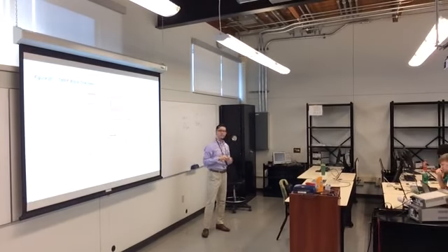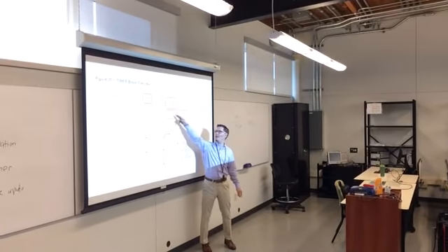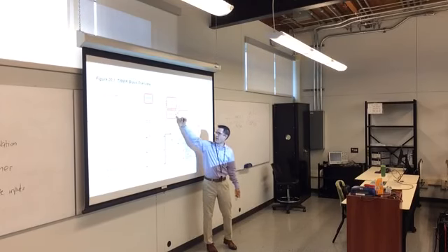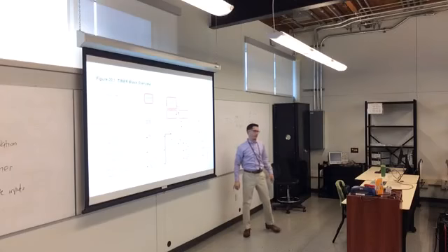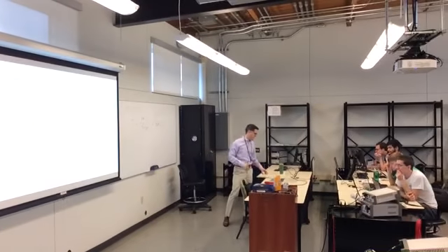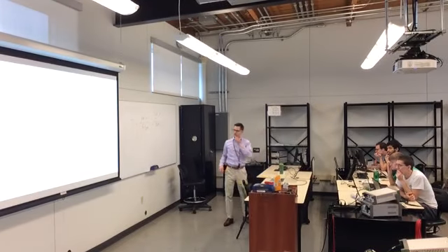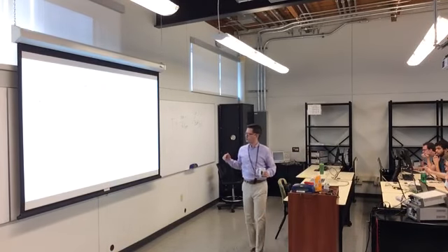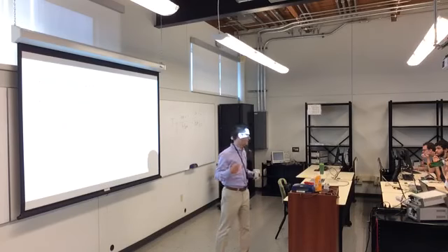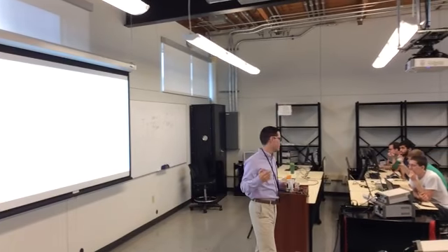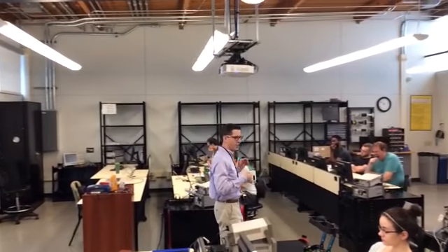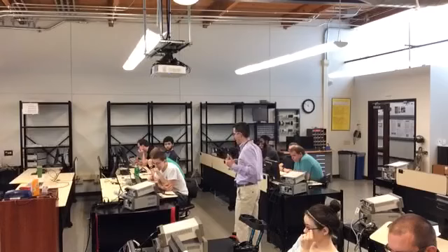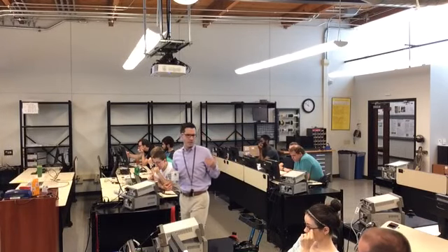And so when the count in the timer is equal to top, you get overflow. And when count is equal to 0, you get underflow, because the next thing it'll do is underflow. So the 4 major registers that you're going to deal with are control, which selects the clock source and how the timer responds. There's command. It's not shown on the diagram, but command is how you actually start and stop the timer. So the timer is not just always running. There's a command register where if you write a single bit to it, it'll start and stop the timer.